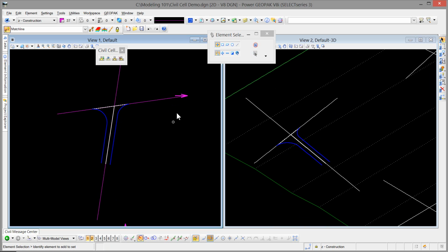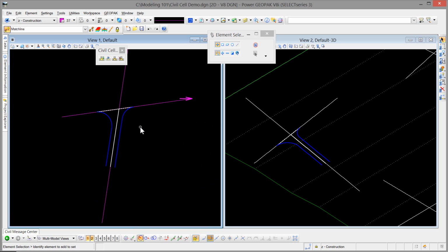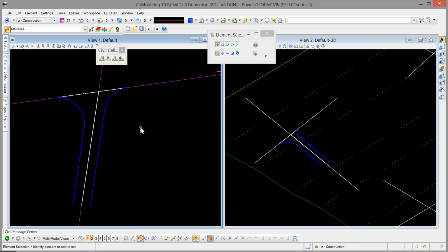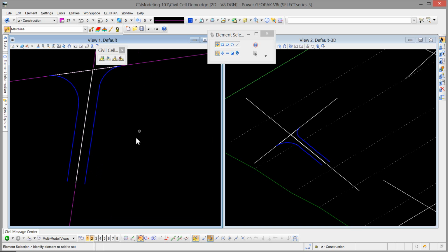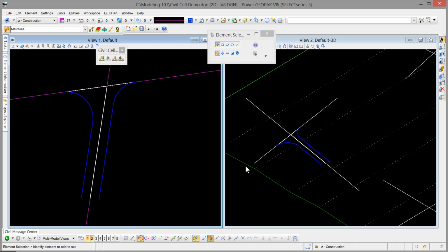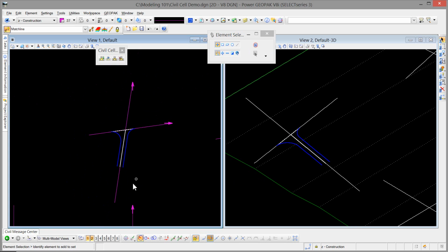Okay, and so that's really critical. And I've seen some people make their mock terrain model like an elevation of 2. Well, it's kind of hard to distinguish 2 from 0. And on this particular seed file, it was meant to be 1,000 meters, which is why it came up to some odd 300 and something. But in your seed file, I would just suggest setting all your lines to something like 1,000. So make your terrain model 1,000, and then maybe put your geometry up in the air a little bit, like 1,003 or something like that, just so you can see some relief.